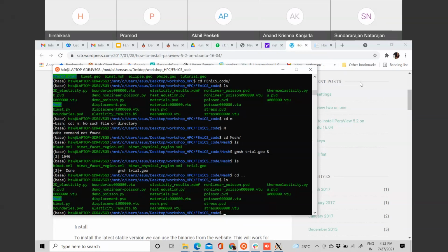No, before meshing, we don't know where the gradient is, right? So for the designing process of the mesh, first of all, we should have some understanding of the gradient of the solution. If you have more gradient, we need to place more elements within the gradient field. So I think for the first starting, we should start with the structured mesh.